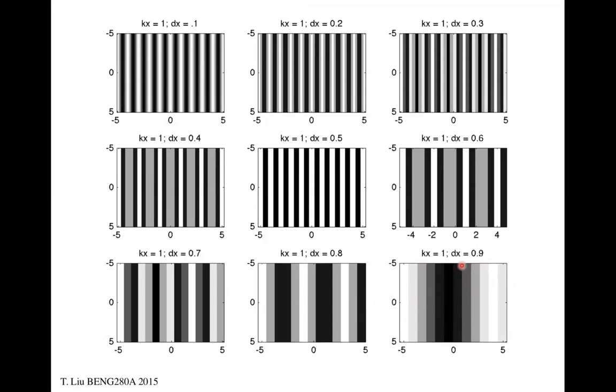And the reason is we're just poorly sampled. We're almost only sampling once per millimeter. What happens if we do sample it once per millimeter? Well, we would sample here, here, here, here. So everything would be the same value. We would just get a constant, and that's complete overlap of those two versions of the Fourier transform, in the sense that DC is now overlapping with our highest frequency.